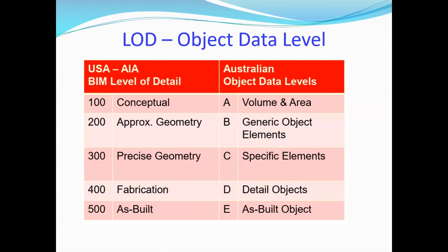What is an object? An object contains information, but what level of information we are giving at that stage is called LOD. I think now it's clear what LOD is. They may use different terminology for LOD in different countries, so I put two different standards, US and Australia.